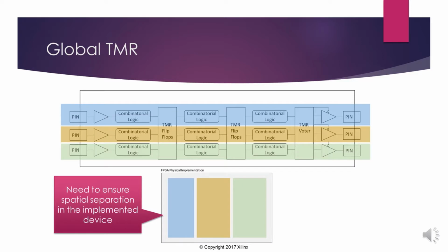So if we look at what this looks like in the FPGA, you can see there are 3 streams: a blue, an orangey colour, and a green one. And you can see that between each stage there are 3 elements of this. Now what this shows is that we also synchronize between the flip-flops at each stage to make sure that any errors in the TMR get resynchronized.